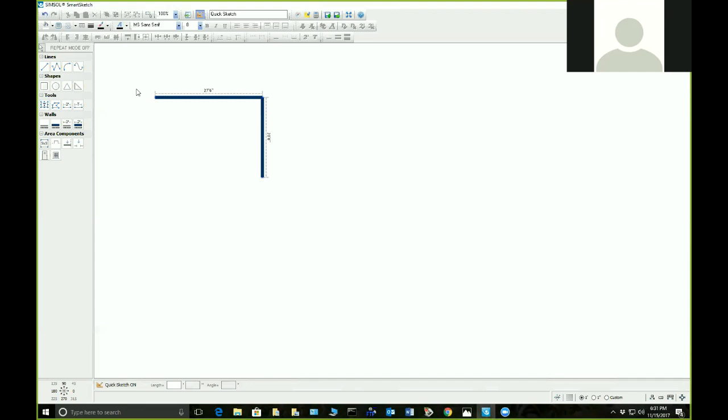Now, you can divide this up if you want. The little trick is if your entryway is about 8 foot in width, I can just come up in here, hit 8, and then select the arrow travel. Then let's say that bedroom number 1, it goes into bedroom number 1 on the exterior wall, and that can be 14 feet.